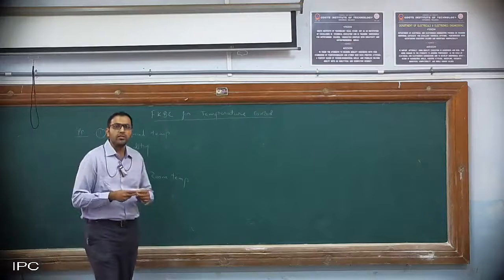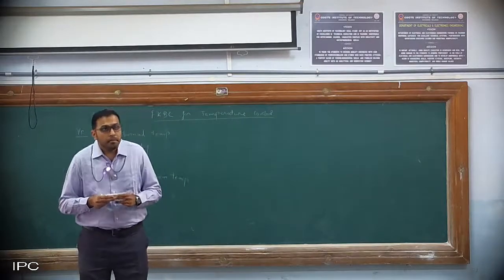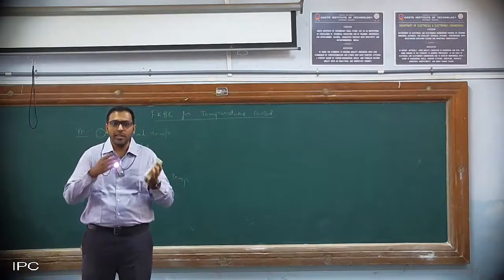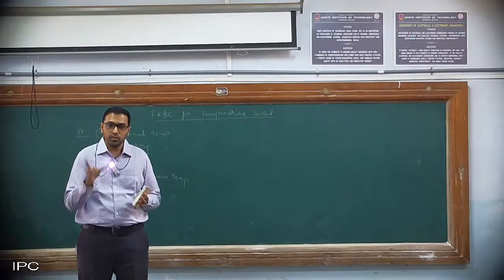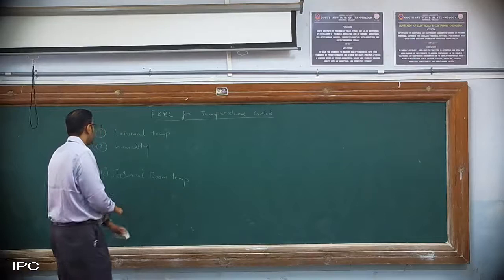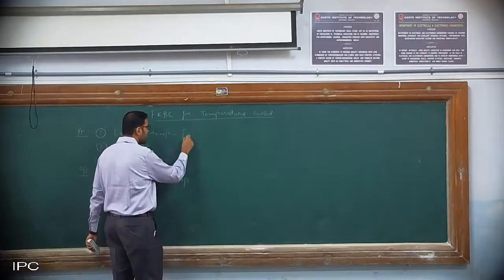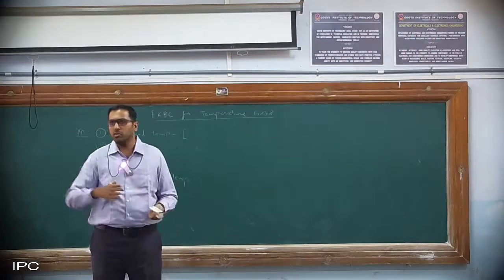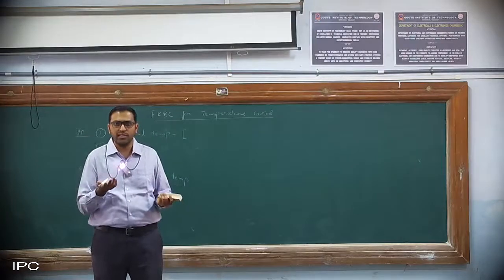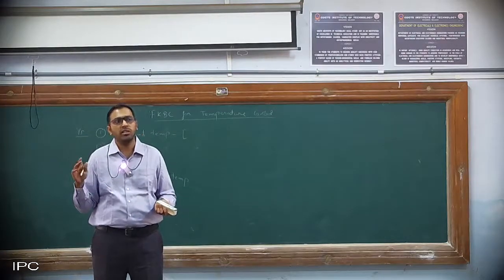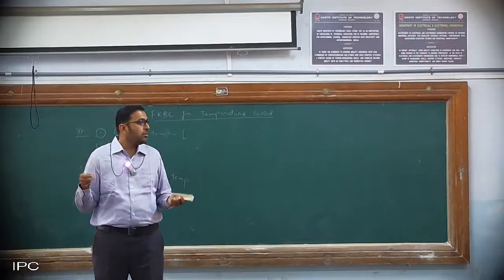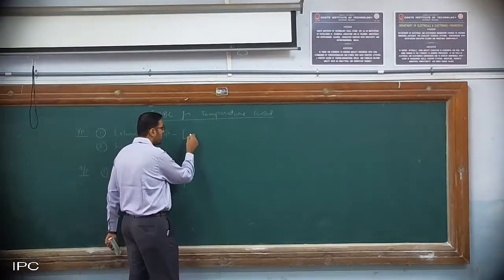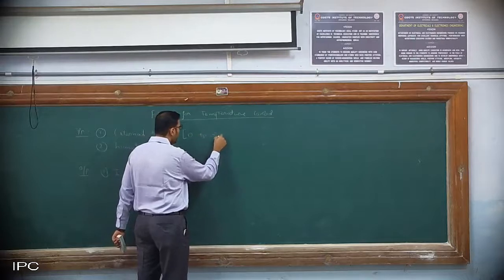So now we have selected our input and output parameters. Now the next step is we need to select the range. We cannot design a system for an infinite range. So we have to select our range. For the external temperature, let us say we are talking about the Belgium region, our external temperature varies between 6 or 7 degrees, which is the coldest temperature recorded, around 6 to 7 degrees Celsius, and the maximum temperature recorded was around 35 to 40 degrees. But in order to have a broader range, we can have a maximum range of temperature for the system as 0 to 50 degrees Celsius.